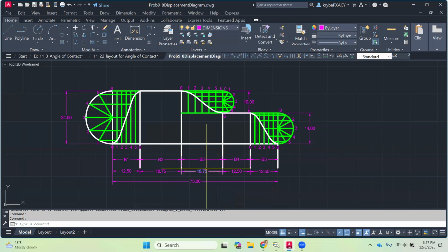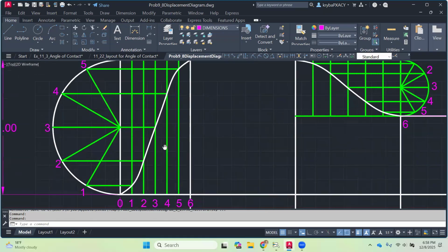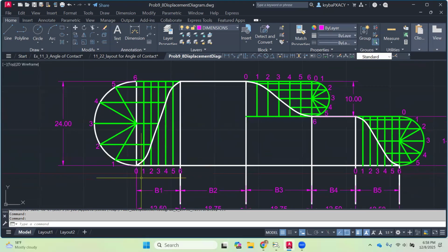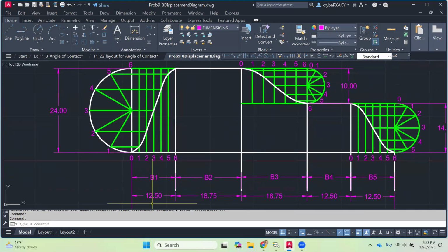All right. Any other questions? So that's where the 75 came from. And then our betas are going to be the multipliers for the distance per degree. Okay. Now let's look at harmonic motion. Here's how we create it. My first chunk here, I'm going to zoom in. My first chunk, my length is 12.5. I need to divide that into 6 even increments.